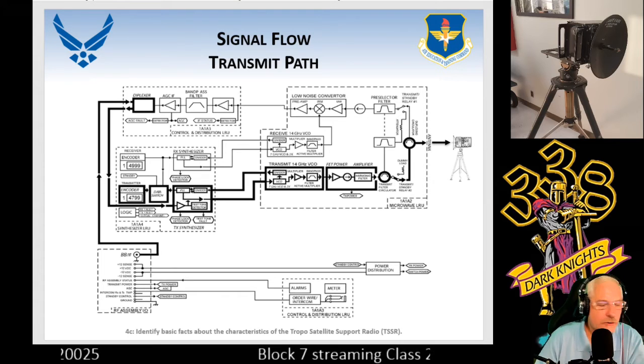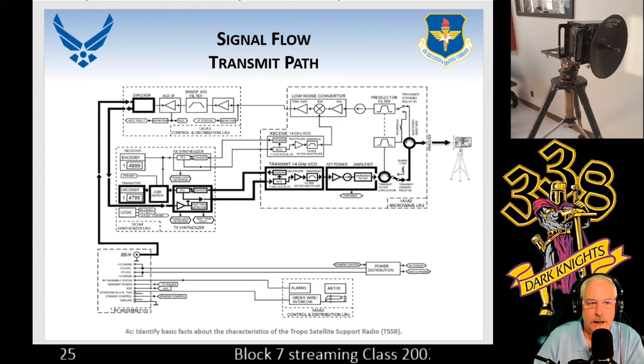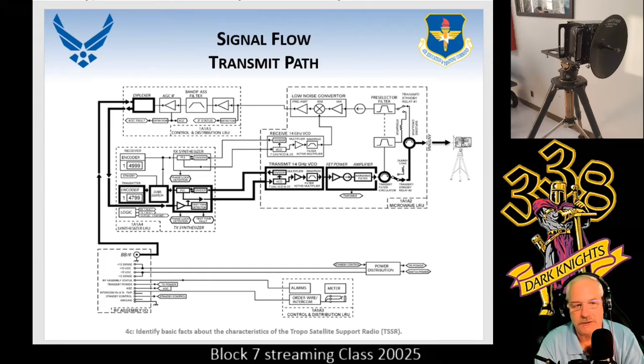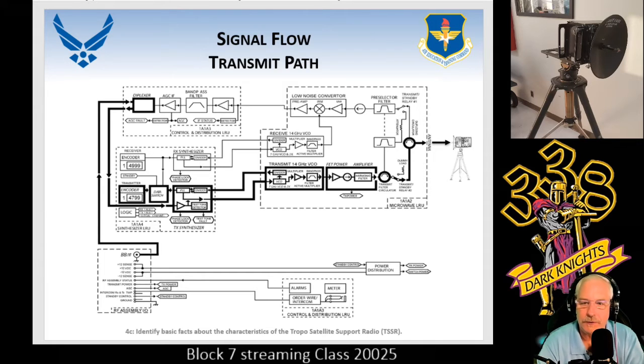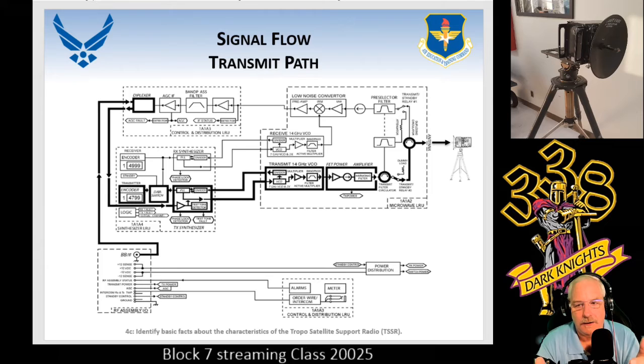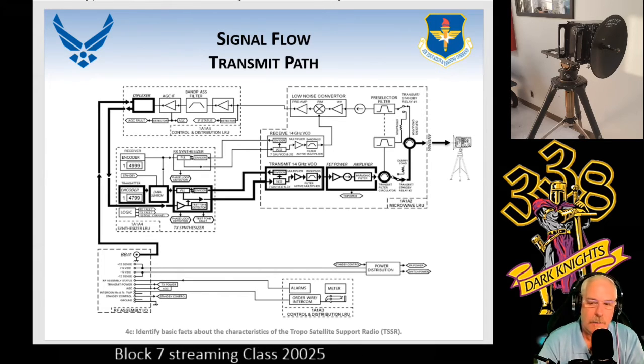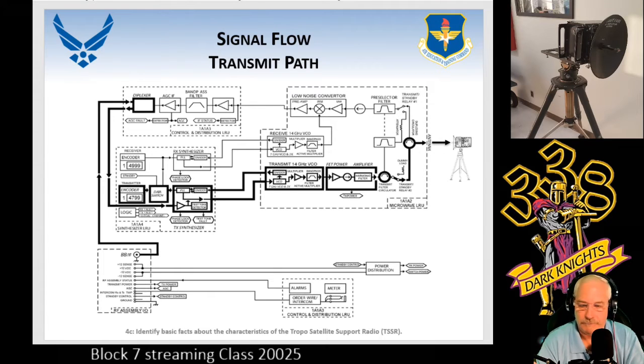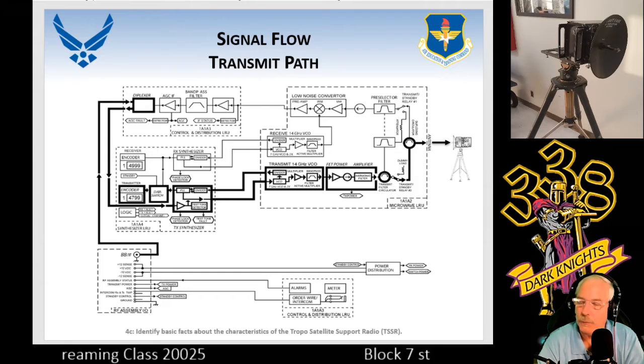So we've gone over the transmit path. I've shown you the part where the branch assembly starts to come into play. We went through the basic objective of transmitting baseband to the distant end by modulation to IF to RF, which is up conversion, and RF amplification, and then we hit where it starts at that isolator all the way out. That is your branch assembly on the transmit side.